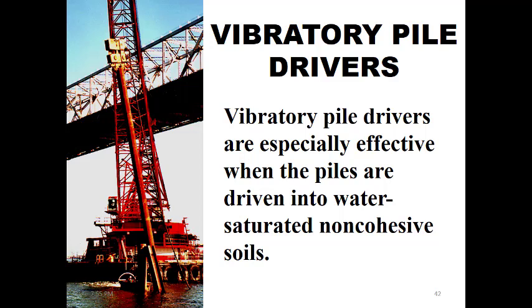Vibratory piles. These are used for moving these piles into water-saturated, non-cohesive soils. Because of that media, it can be really preferential to use these vibratory piles and drive the pile down. In the picture is the pile that is standing. Actually, it's positioned through the crane and the lid. And on the top, you should notice these square shapes at the end of the pile. That's the vibratory pile driver.